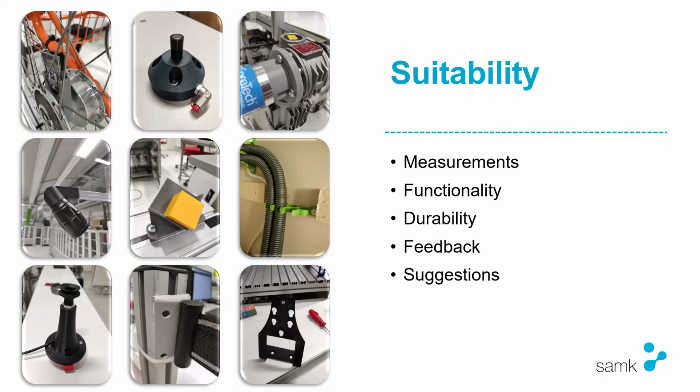So, usage and iterations. Check the suitability. Does the print fit its need? Check the measurements, check the functionality. Is it durable enough? And get feedback and suggestions for that print. If, for example, the feedback shows things to improve, go back to the 3D modeling, make the changes, and print again.